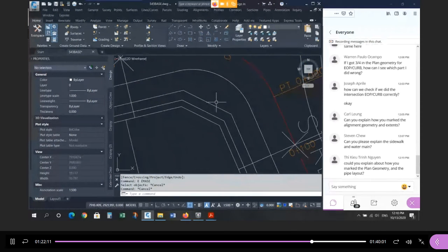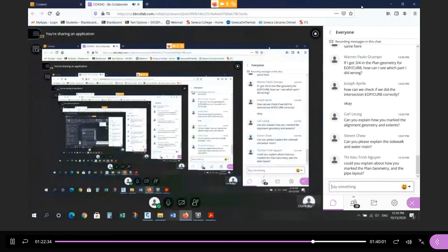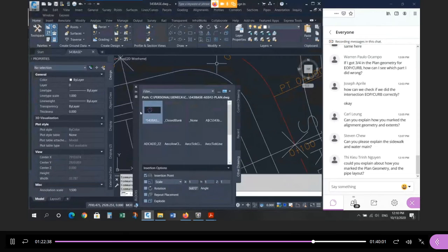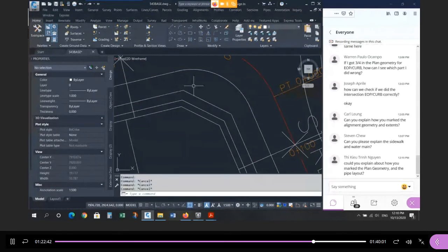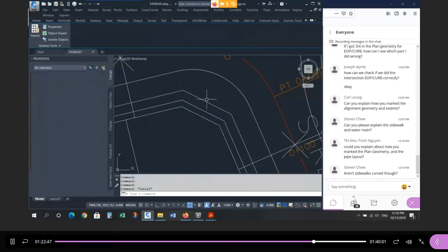This, strictly speaking, is exactly what I would do with the sidewalk. There's a couple of options here. You could extend the sidewalk, offset 0.2 to the back of curb. A second, closing. Computer's frozen in there. Okay, so this is what I would have drawn for the sidewalk, right? 1 meter in from the gutter, from the street line, and 1.5 meters wide.